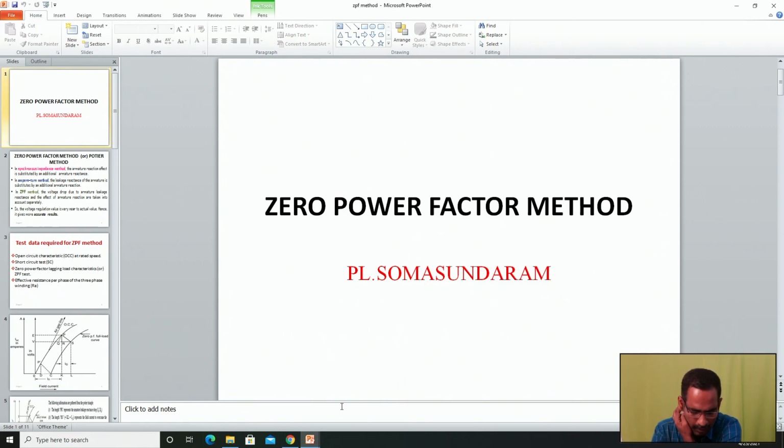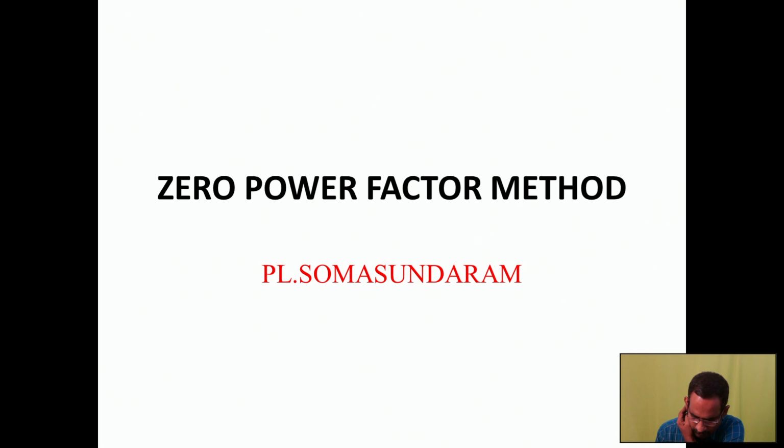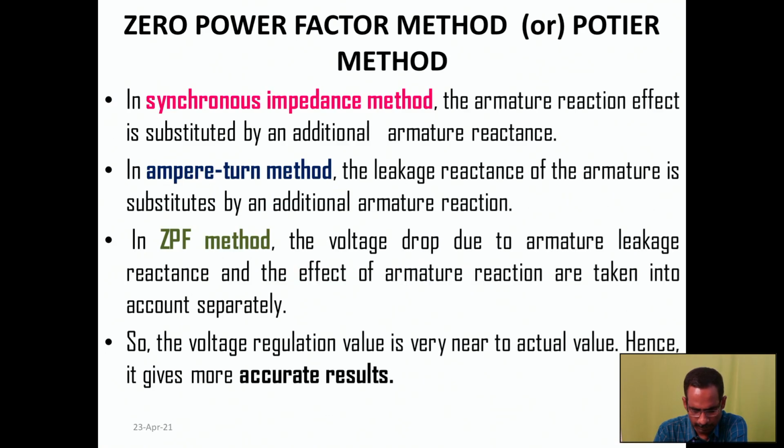So next I will move to the next method, the zero power factor method. So what is meant by the zero power factor method? Here, additionally, with the no load and blocked rotor tests, I need one more set of data, the zero power factor test data, that is also required here. In the zero power factor method, it is also called the Potier method.